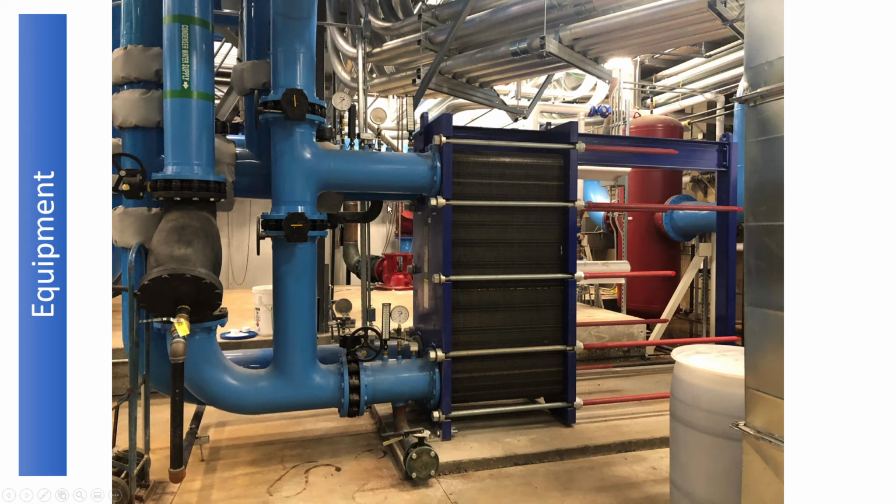So basically what we're doing is taking water from the cooling tower and making cold chilled water, and what does that mean? You don't have to run the chiller. So when we saw 84 kW on the chiller, it'd be nice not to have to pay for that 84 kW, right? If we can just exchange water right here in the plate and frame heat exchanger, then we basically have what we call free cooling. You'll also hear this called water side economizer. Water side economizer, plate and frame, those are the common terms for this kind of energy efficiency option in a chilled water plant.